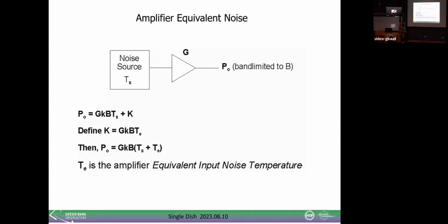After you get past the low noise amplifier, there's enough gain so your signal level gets high enough that the added noise from components after the low noise amplifier is really small, less than 1%. So we really don't have to worry about the components after the low noise amplifier.